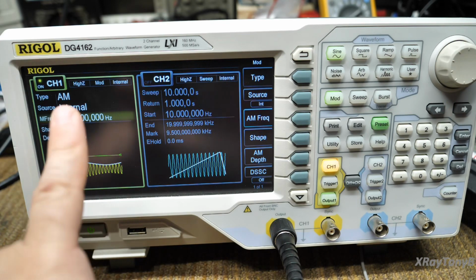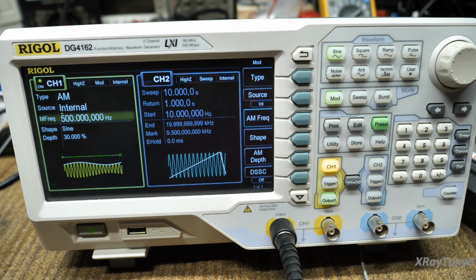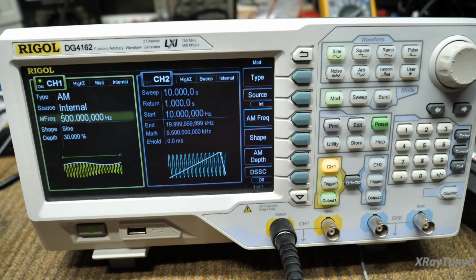A radio, first of all, tunes into that carrier, which is the 600 kilohertz. Then it detects that sound that's riding on that 600 kilohertz, takes away the 600 kilohertz, and only leaves behind the sound that you hear with your ears, and then amplifies it so your speaker can make it loud enough so you can hear it. That's really what this is all about.